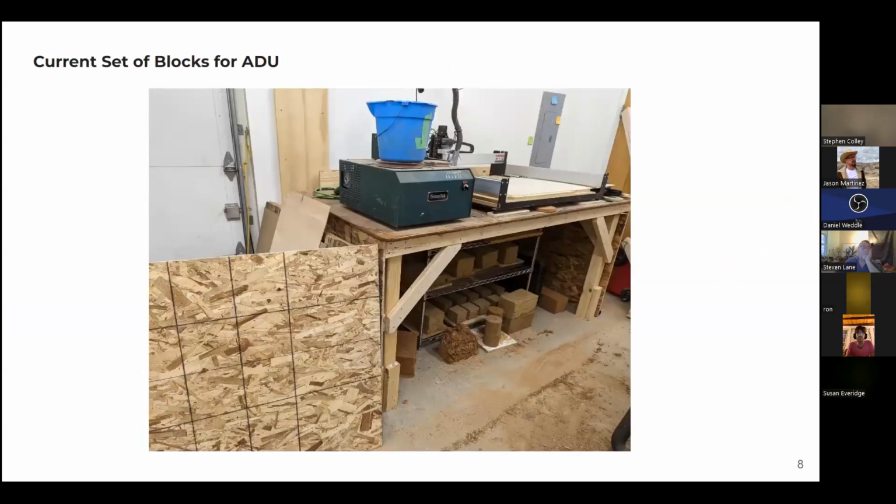This is our drying chamber. I'm going to show you a few not super good shots from the lab, but this is just the day-to-day. This is the dehumidification chamber. We keep it at about 105, 108, which keeps us from having any sort of over-baking results pushed into our numbers. Right now we've got about half-weight cob we've developed that's stronger than traditional cob, or at least our traditional cob mixes.